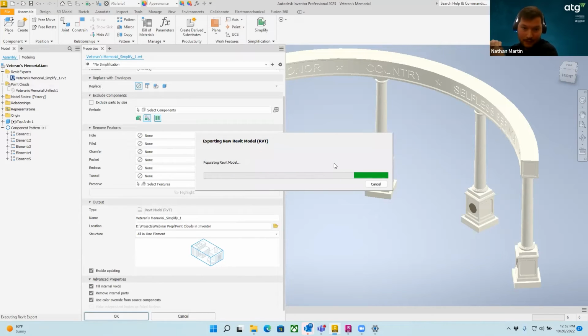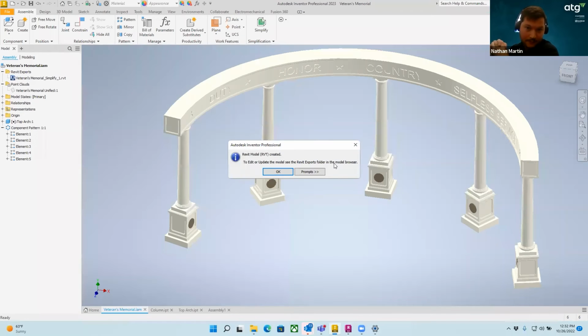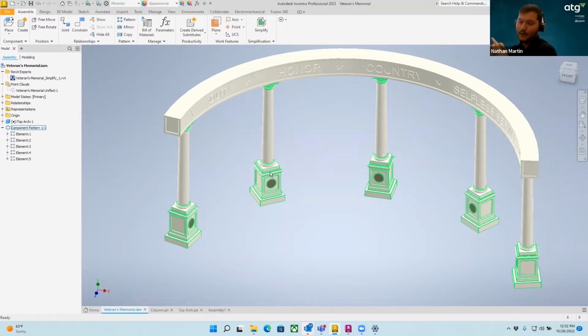We're at it again. Have you ever taken the point cloud and converted it to mesh before bringing it into Inventor? No, I haven't. But I know if you have a lower end computer, if you convert that over into a mesh, Inventor and other programs tend to like that a whole lot better when it's in an STL format or some sort of triangle format. So it would be easier for the computer to handle it.